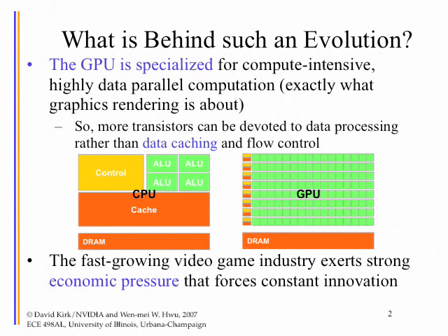The reason is that the CPU design philosophy is to get as much data as possible to sit on the chip so that the CPU can access the data with very short latency. Essentially, single cycle for first level cache, about 5 cycles for the second level cache, and about 12 cycles for the third level cache, compared to hundreds of cycles if you needed to go to DRAM.